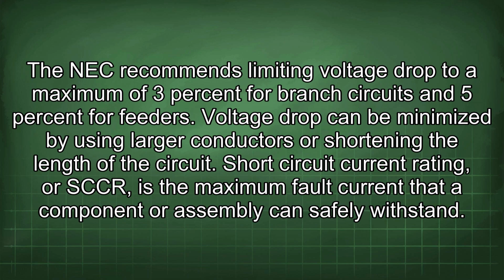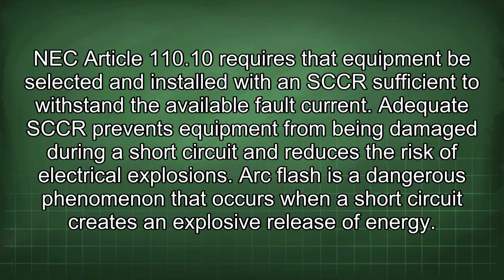Short circuit current rating, or SCCR, is the maximum fault current that a component or assembly can safely withstand. NEC Article 110.10 requires that the equipment be selected and installed with an SCCR sufficient to withstand the available fault current. Adequate SCCR prevents equipment from being damaged during a short circuit and reduces the risk of electrical explosions.